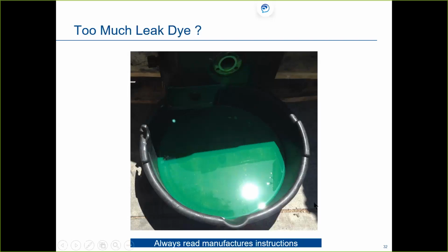It's amazing how much. And when you put this in here, do you think that's running inside the envelope? Have we thrown that chemical, that refrigerant off, that blend? We sure have, okay? Our PT charts probably wouldn't even work with this inside the systems, okay? Always read manufacturer's instructions.